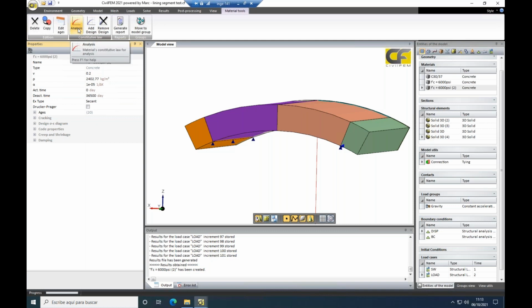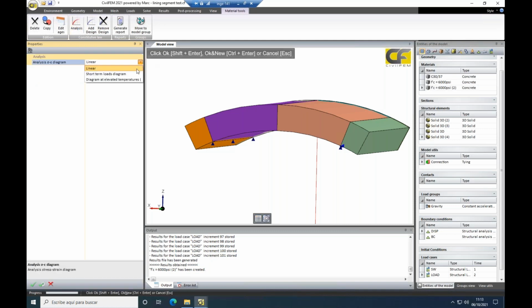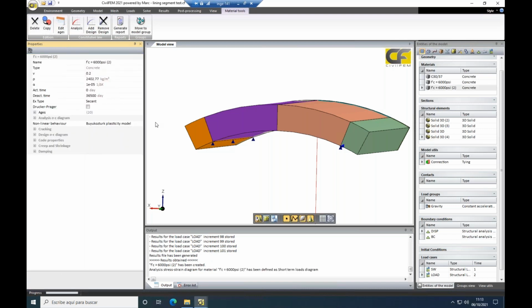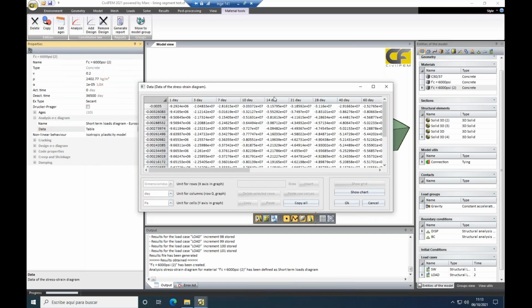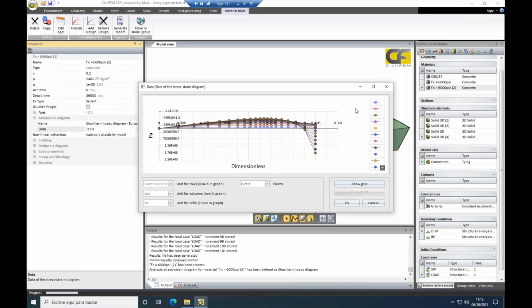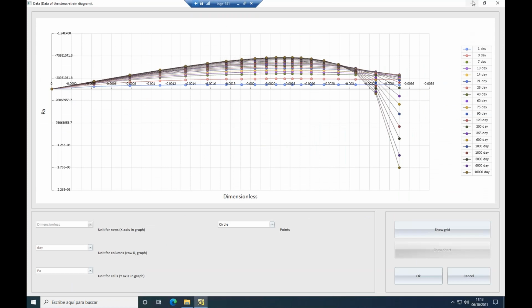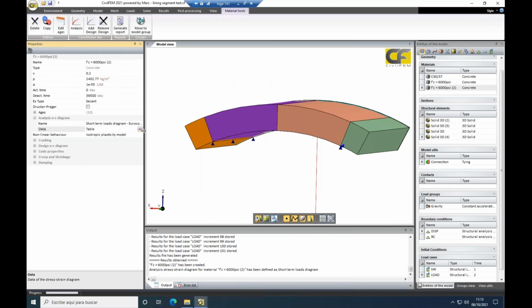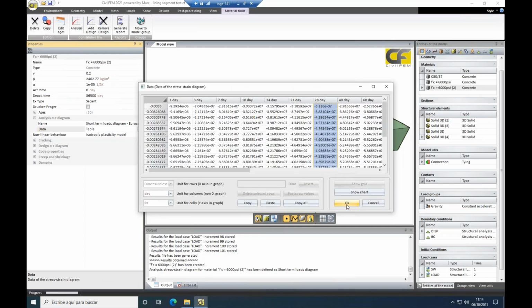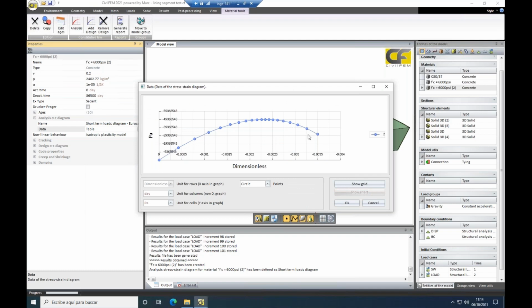The first step is to convert to nonlinear behavior for compression. So I'm adding certain loads and an isotropic plasticity model. Now the analysis diagram that I'm using for solving are these time-dependent material properties. Fiber reinforced concrete behavior, they don't have, so I'm going to select the 28 days only, just for you to see it. All those graphs are time-dependent material properties, so you have many curves.